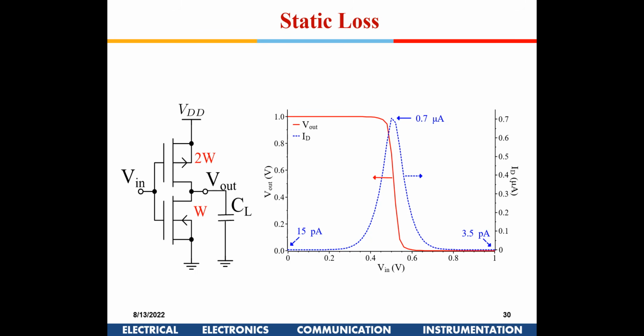There will be a diode which will be reverse biased. So now, because we have to reduce the threshold voltage, that diode has become a very weak diode. And because of thermal emissions, there will be a small current which will flow. Okay, it will be in picoamperes, but since we have billions of transistors in a core, if you multiply this picoampere by billions of transistors, then it will come to a significant current, right? So that is the issue.